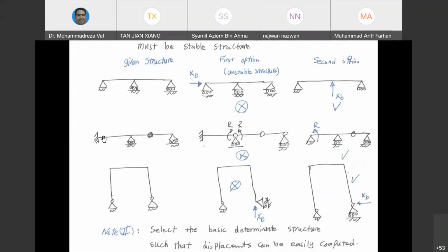Another example is like the second beam here. So again, we have 3 support reaction and we have 1 internal hinge. So as I said, you can assume that the bending moment here is the redundant one, like the one that you can see here. But the moment that you put a hinge there, because when you remove the support reaction, you need to put the support reaction, meaning the bending moment here should be 0.